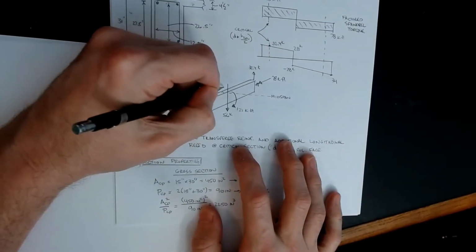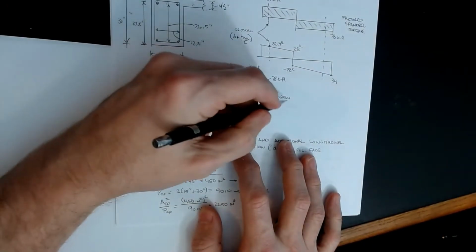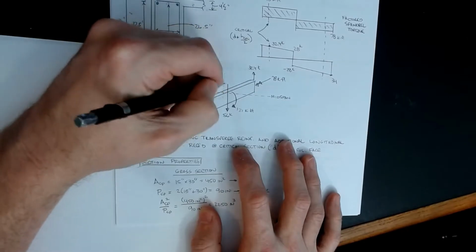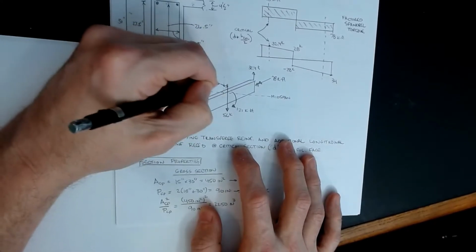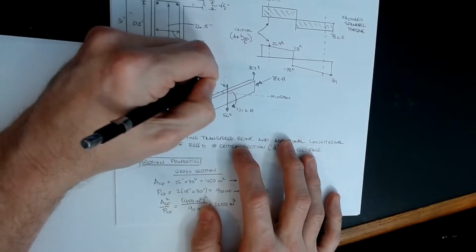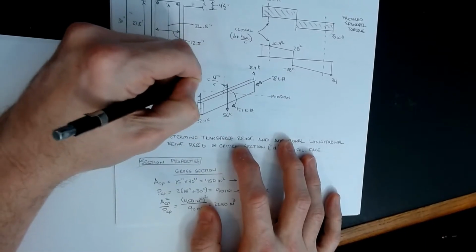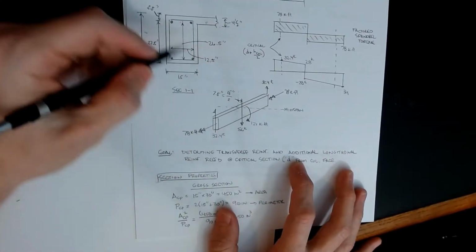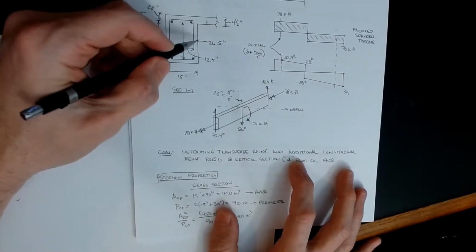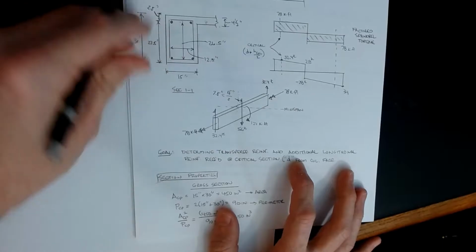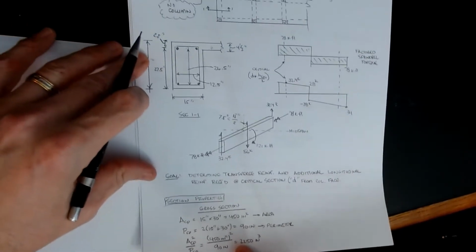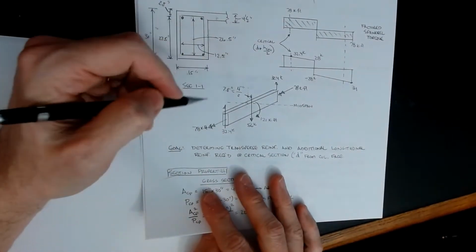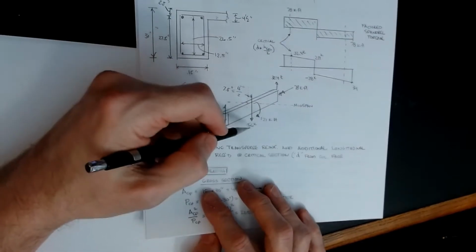Okay, I did leave off one dimension. If the dotted line here is the midspan of the beam, there's an eccentricity of that shear force in the amount of 15 inches over 2, which is 7.5 inches. So this is at the face of the beam that's tying in. A beam is coming in and it's tying in on this edge of the cross section. You guys see that? So it's 15 inches eccentricity from the middle of the beam to the face. That's the 15, so 7.5 inches. We'll need that. And that reaction is 56 kips.